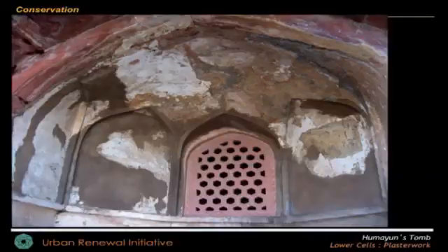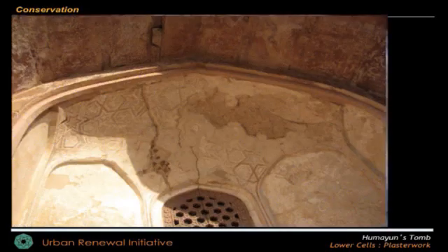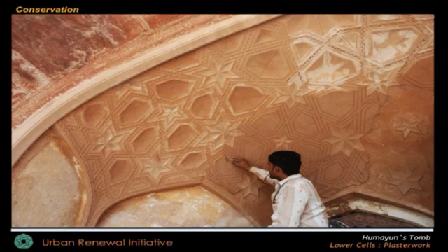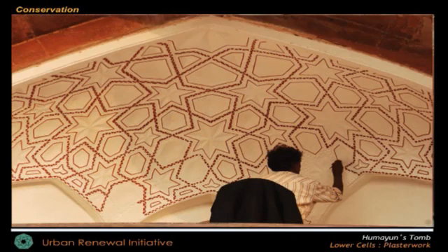This is the base layer. So the lime is applied in several layers. This is quite thick, 3 to 4 inches. And we put in the patterns. We had to train craftsmen for this. We needed 3D laser mapping, 3D printing to make sure that these patterns were exactly right. Now, all that science of geometry I'm unfortunately not able to explain, but all of these patterns were restored, and then the lime and the red were going back.